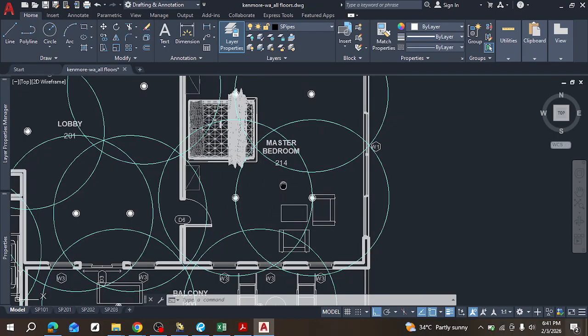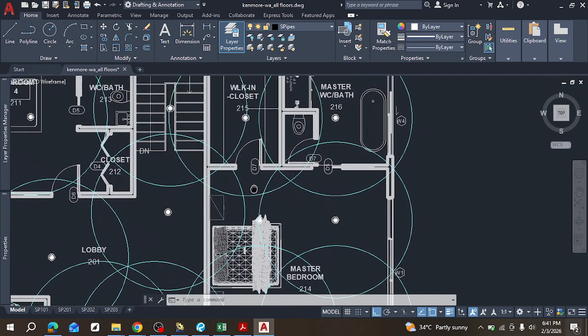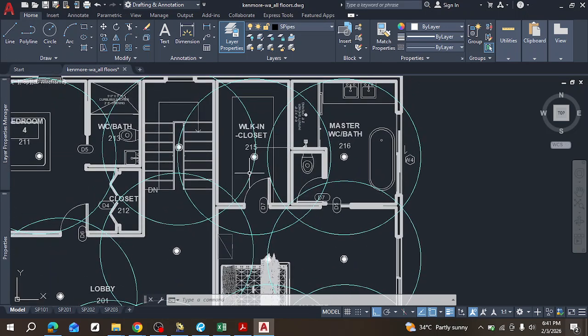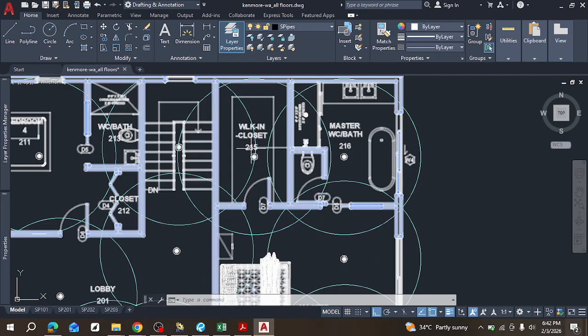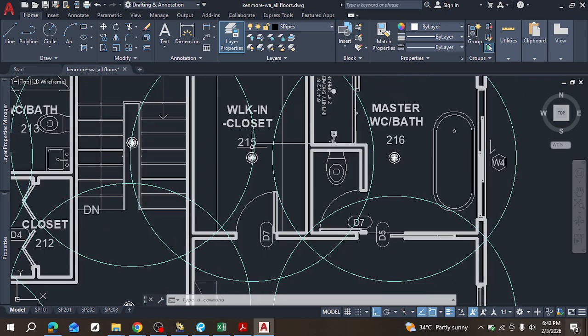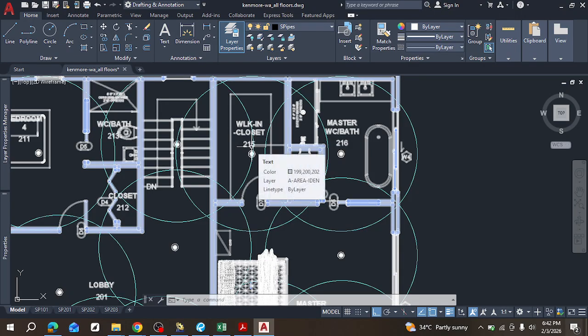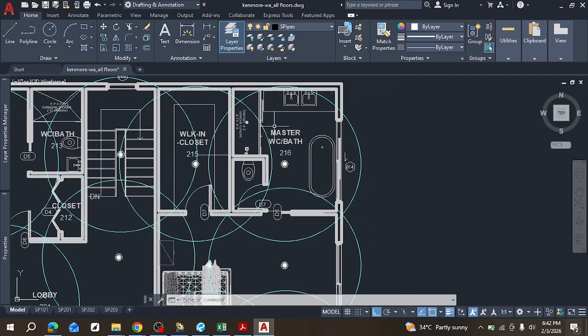This is it. So now this even has a walk-in closet. This is the largest bedroom in this building. There's a walk-in closet, right? And this walk-in closet now has size limitations. It exceeds the size limitations, so there was need to put in fire sprinkler. That aside from the fact that walk-in closet has items that are also fire hazard. Once there's anything like a fuel or cloth or something that can catch fire, it elevates the hazard level of that space, right? So then we have a bathroom.